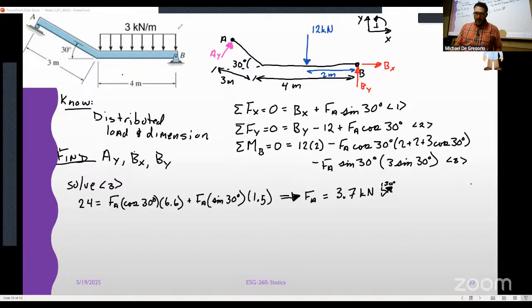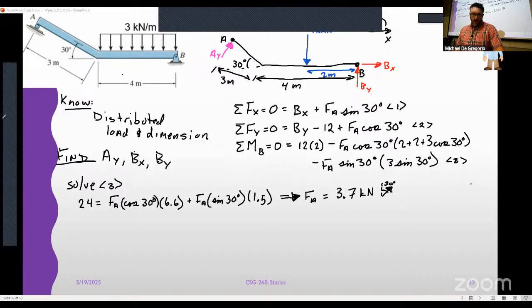So, all right, let me do it this way. So this force here, you can break this down into x and y components. I've got some component that goes this way and some component that goes that way, at point A. The angle between the vertical, or let's draw it over here, this angle is 30 degrees. I know that's 30 degrees because the x-axis is off by 30 degrees. I'm going to make this less cluttered.